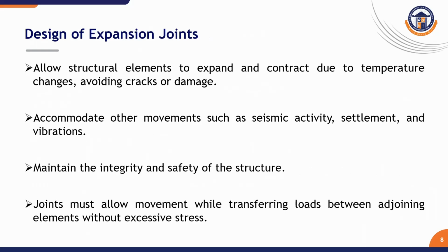So, design of expansion joints. Expansion joints allow the structure to expand and contract due to temperature changes, seismic activity, settlement, and vibrations. The key considerations in expansion joint design are to handle the maximum expected movement from expansion, contraction, seismic force, and settlement, transfer structural loads smoothly without causing any damage, and provide effective seals to prevent water, debris, and contaminants from